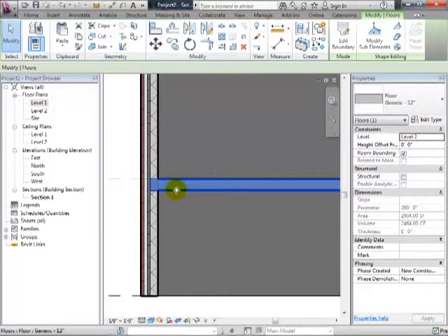And all you need to do is just change it ever so slightly. I just want it to move, you can move an inch or whatever it is. You can put it back if you want. Now say finish it. And this time it'll realize, hey, there's an intersection, and ask you whether to cut it out. Say yes. Now let's go back to your section view, and you'll see it's actually looking pretty good. Wood joists actually do pretty good in terms of the way they're looking here. They're not really omnidirectional, but when we render them in 3D, often they don't look very different.